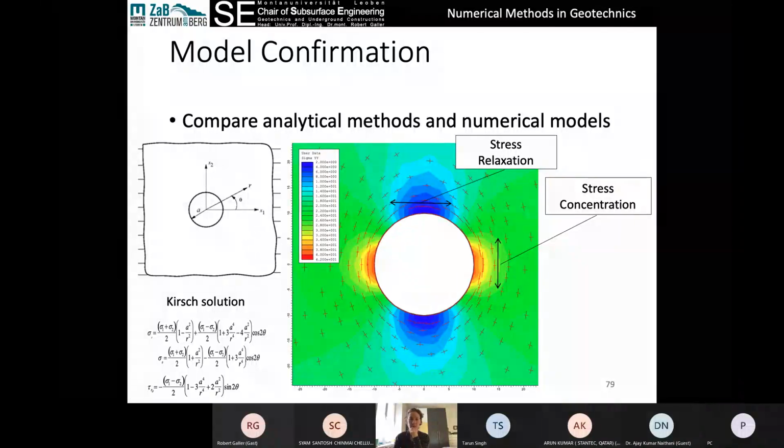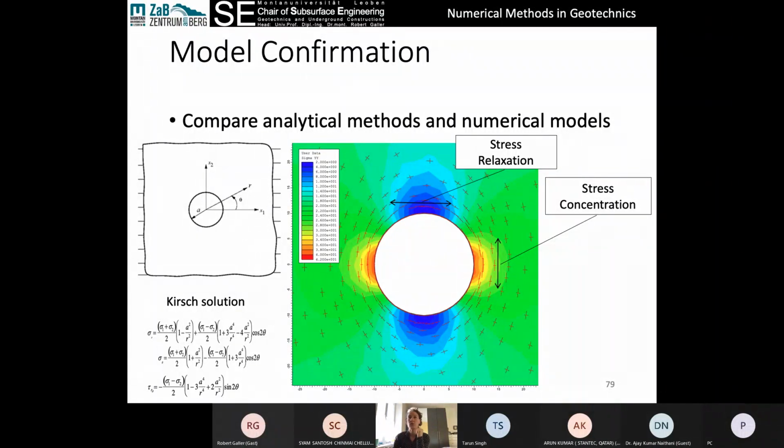So it's that calibration. And then also with the stresses, right? Making sure that the stresses are properly calibrated. Are they too high? Are they too low? Are they in the right orientation? This, for example, is a situation where vertical stress is the highest and the horizontal stress is the lowest. We can look at the stress vectors here that show us that. And our stress concentrations are here on the sides. We would expect shear failure here on the sides, and we would expect a little bit of tensile failure here at the top and bottom.